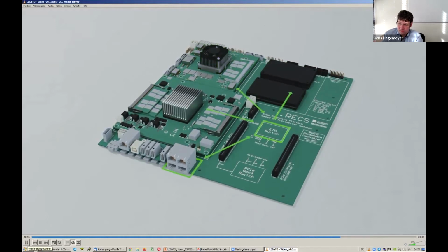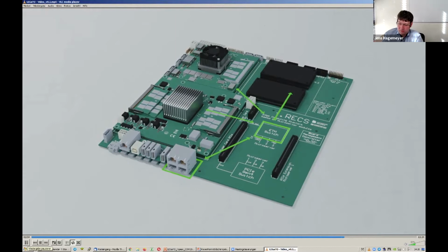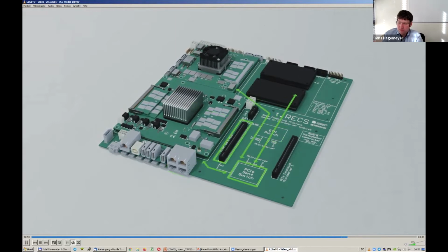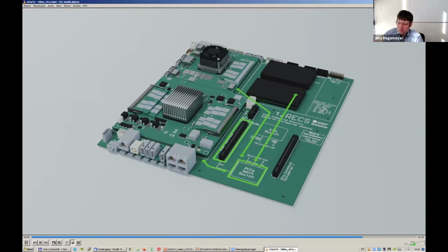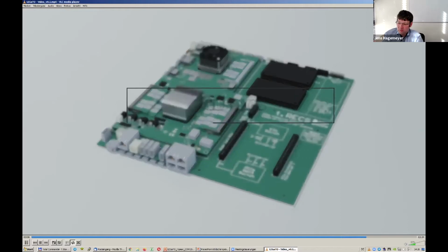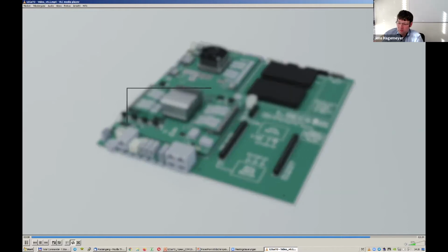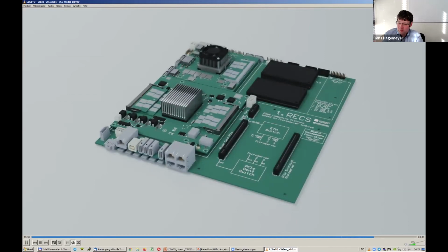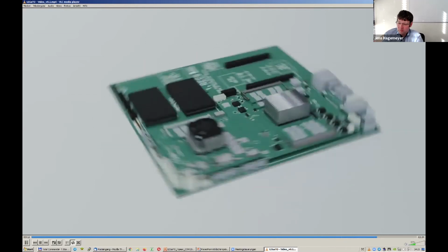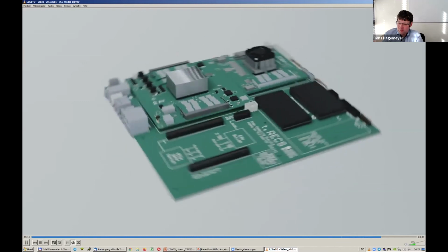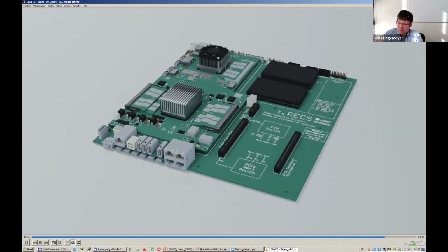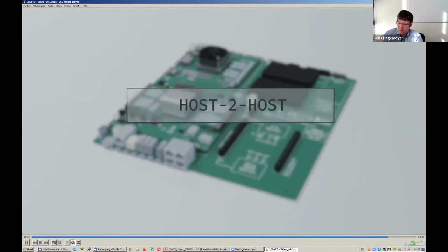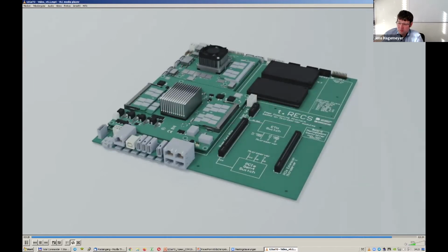The Edge server integrates a 40 GB Ethernet backbone as well as a high-speed, low-latency communication infrastructure based on host-to-host PCI Express between the different compute nodes and peripherals. This infrastructure provides various topologies and even shared peripherals across multiple hosts. In contrast to traditional PCI Express switching, not just communication to peripherals, but also direct host-to-host communication is supported.